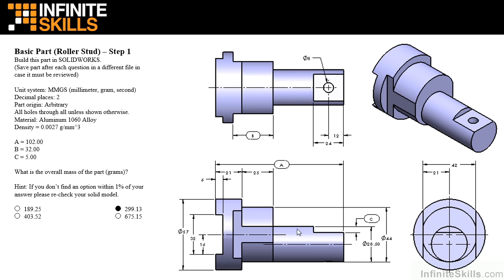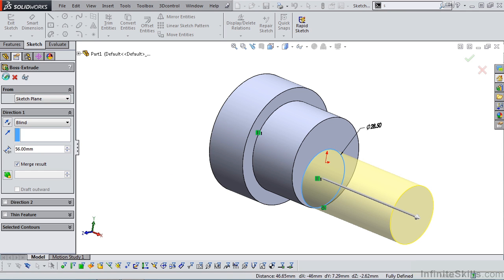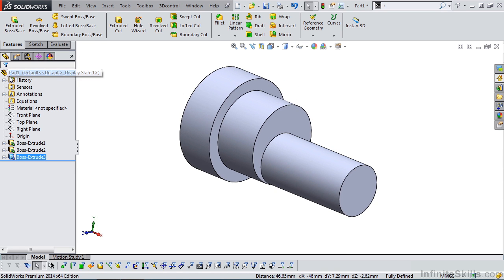Viewing the drawing, it appears that we do not have this dimension given to us directly. However, we do have the A dimension of 102, and we have these two dimensions of 25 and 21. So in the SolidWorks screen, I can simply type in 102 minus 25 minus 21. I'm going to go over to the Property Manager and type in 102 minus 25 minus 21. I'm going to close out of the Property Manager, and the feature is extruded. So this is one approach to creating the 3 cylinders on this part. In the next lesson, we'll take a different approach.